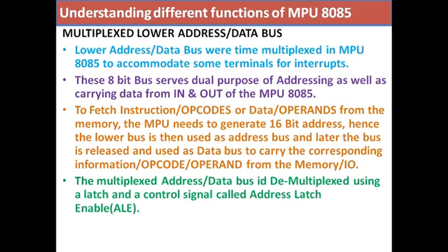The demultiplexing can be carried out using a latch and a signal that comes out from ALE, which is otherwise known as address latch enable. We will take up the demultiplexing portion in the next lectures.